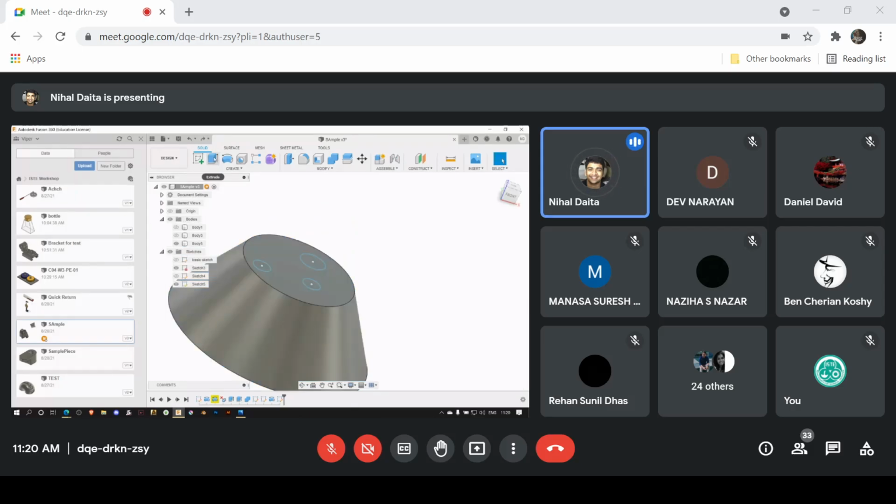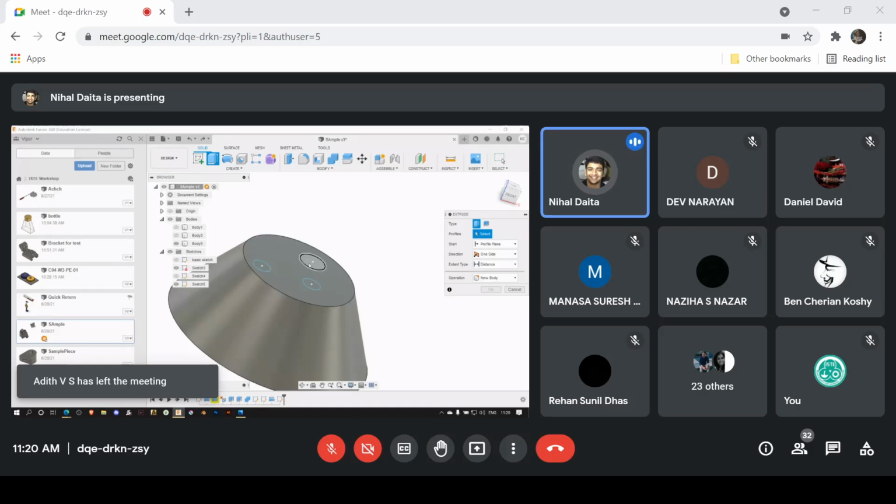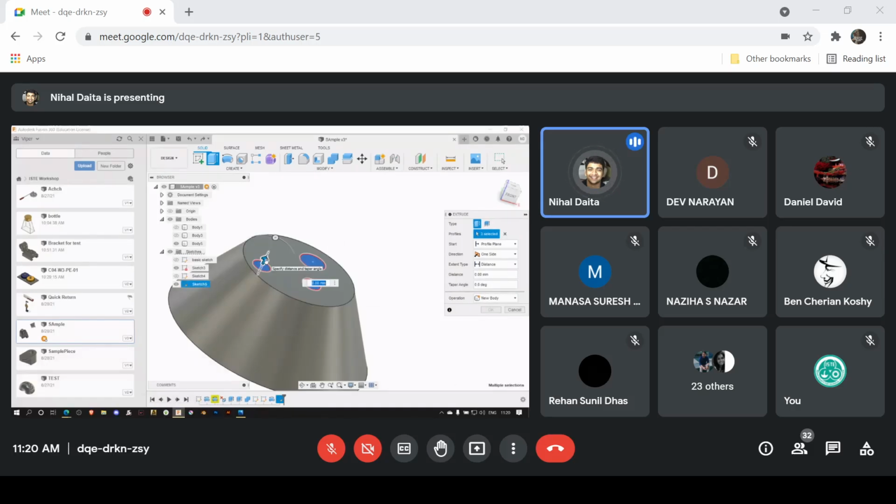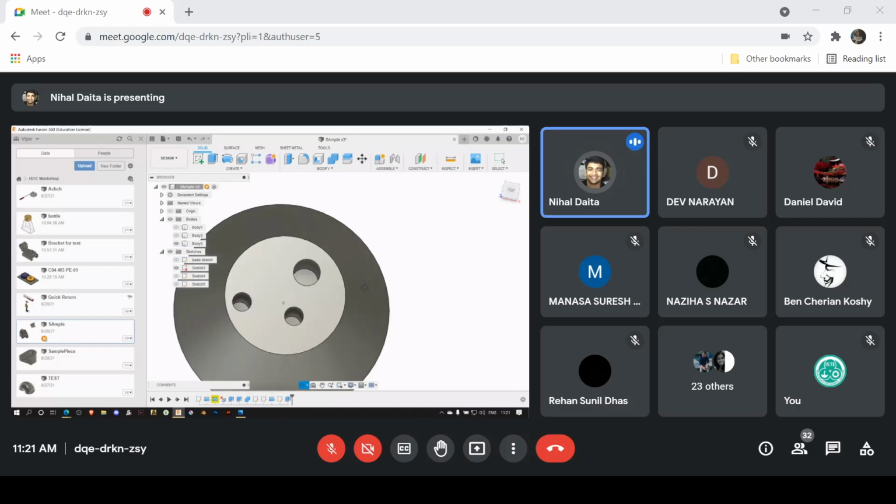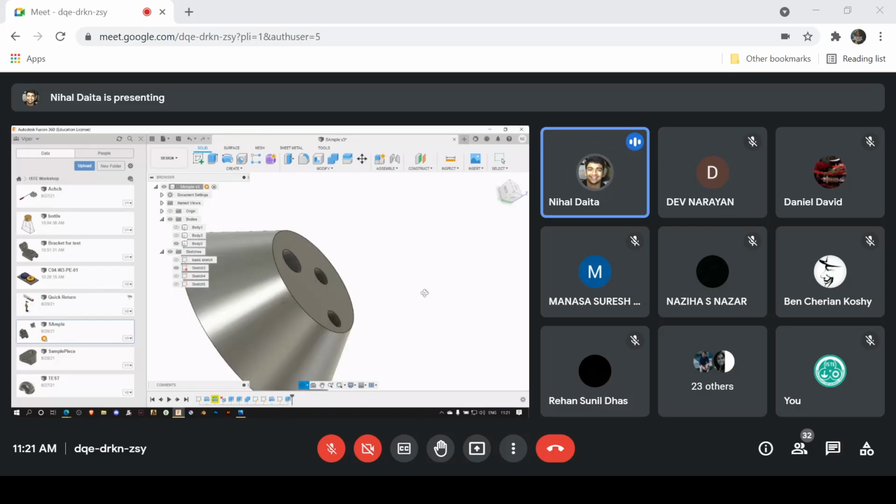So similarly, there's another feature of extrude, right? I have shown you how to make holes on surfaces. As I've shown you earlier, if I click on these, the arrow usually points outwards as a default option. I can pull it out. At the same time, if I pull it in, as you can see, the red denotes that it is drilling, or it's just creating a cavity into the existing surface. So I just click OK, and as you can see, it drills into the existing object.